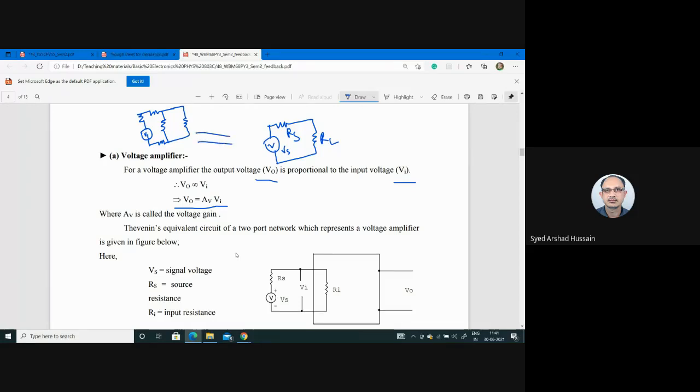So we can write this circuit with several resistances, RL, we can write. Okay. So how will we do it? The main issue is, whatever complicated your circuit, if it is a voltage source, voltage control circuit, you can replace it with a voltage and resistance in series, where the voltage is the Thevenin's equivalent voltage, and the resistance is the equivalent resistance with load. Okay, load is mainly to have the output.